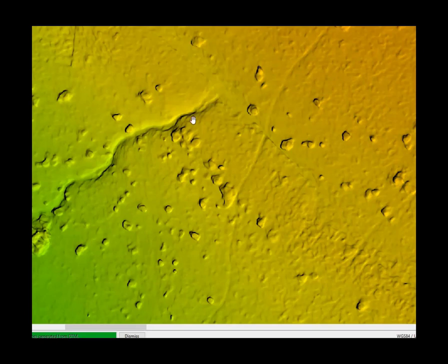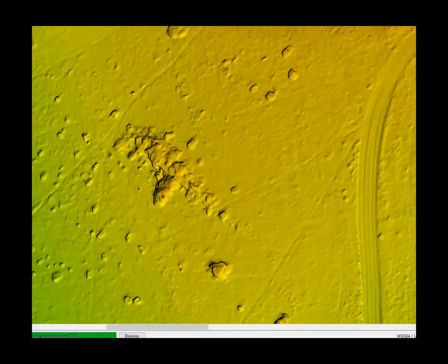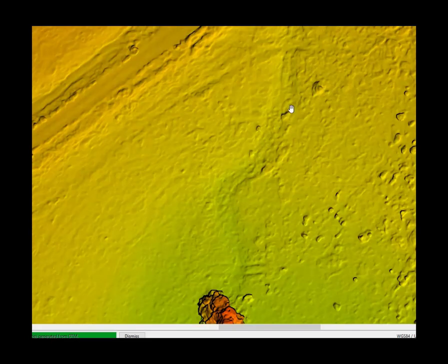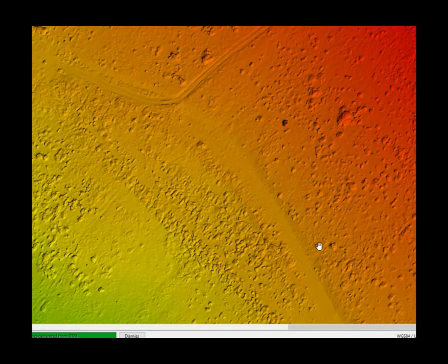The surface model in Pix4D captured that gully in incredible detail. The rock outcrop was pretty much, again, just merged in with the vegetation. This is my vehicle, and I neglected to classify it as a man-made object, so we'll see that it shows up in the contour map. The gully was captured in incredible detail. However, Pix4D has no provision for break lines, so the contours don't necessarily cross the stream. The cut slope on the old road bank was, of course, modeled.